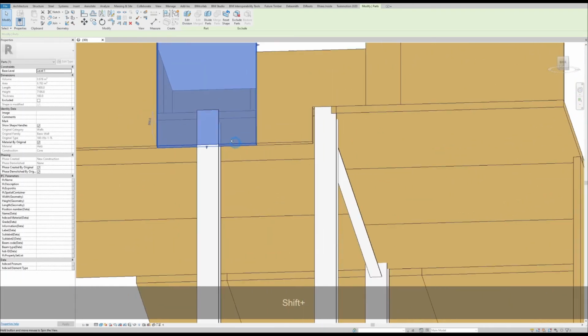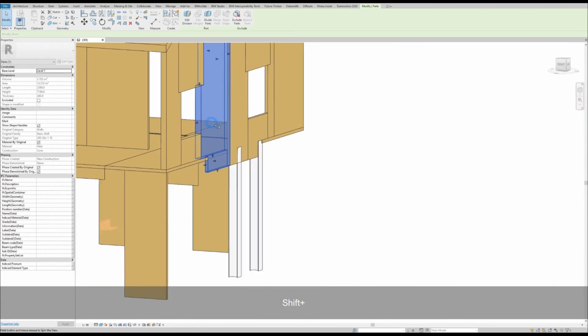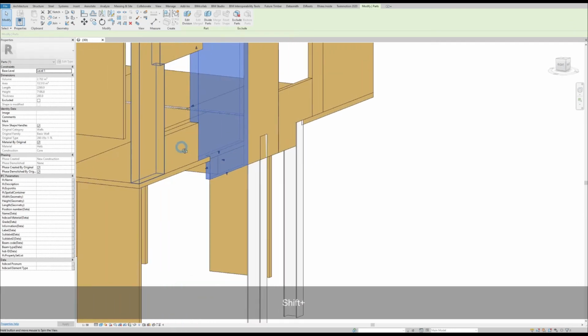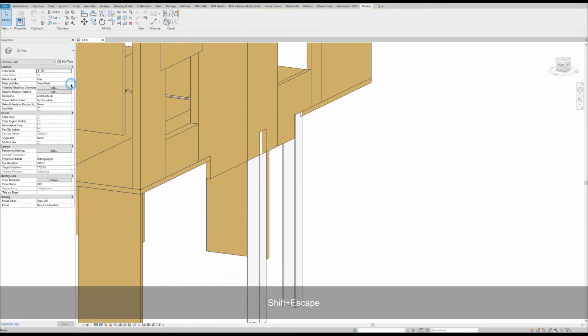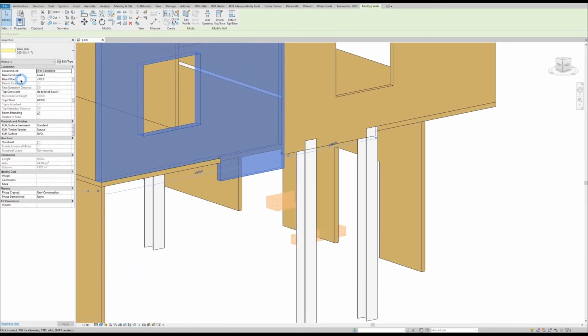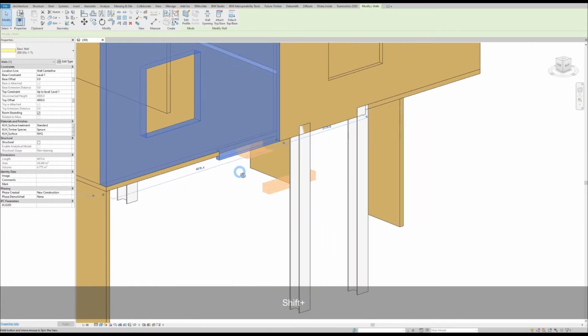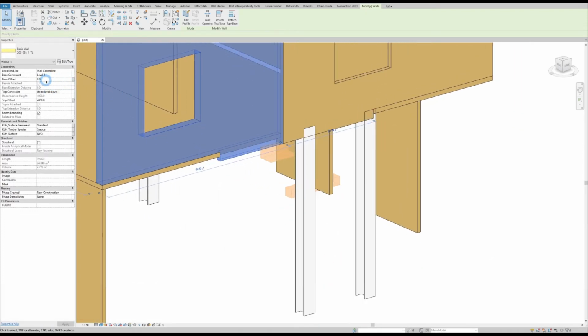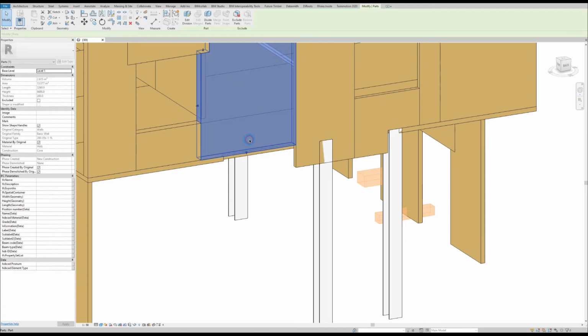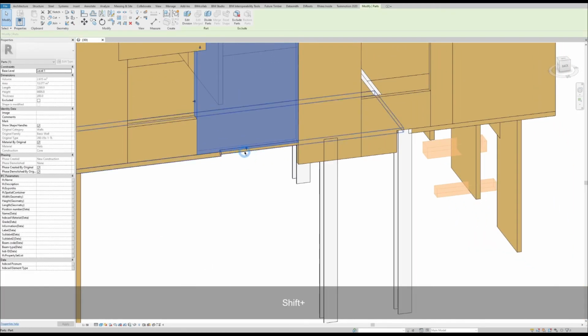Here's an interesting one. The wall is actually thicker, and it is half bearing onto the slab and half over. This was originally controlled by the extension length of the offset. So if we put that back to 0, you see it moves it up and down, or 200 to be at the same level there. So if that is like that, and we go back to parts, you can see we don't have the ability to manipulate that shape anymore.